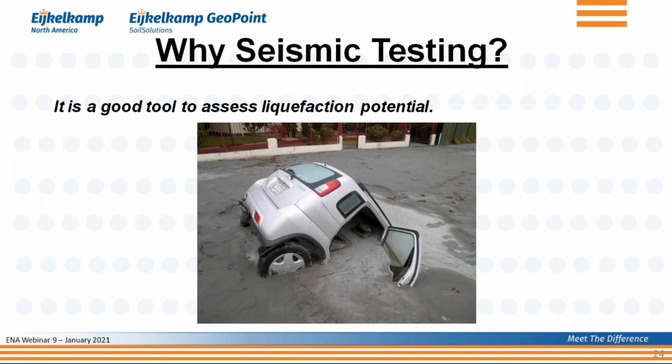On top of that, as I already mentioned earlier, with the seismic CPT, you can estimate the soil parameters, be it the shear modulus, be it the Young's modulus, or even the Poisson ratio, much more accurately as you have it in the field. So for those reasons, you really want to do seismic testing. Apart from the fact that you have to, in accordance with the building code, that's also a reason why you want to. So on that basis, the answer is absolutely, you should do seismic testing,